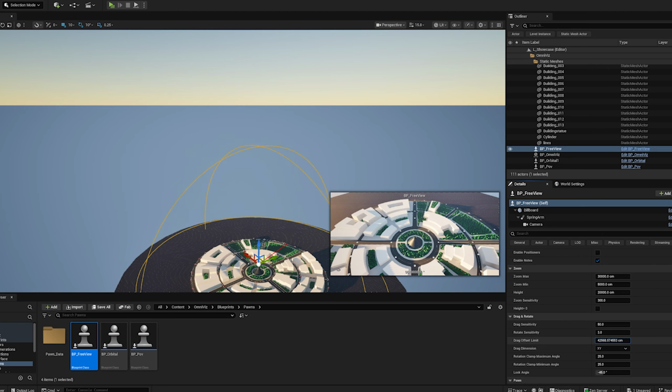Unreal Engine does a great job selling the emotional side of a project, but when you present technical work, you need hard data. We need the ability to take basic measurements in real time. I divide it into 3 modes. Measuring the distance from the camera to a click point, measuring between 2 click points, and measuring a radius. But building this is harder than it sounds.